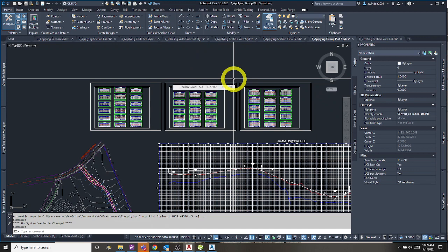When section view groups are created, there's 2 placement options. So these are critical as well: production and draft. And when a section view group is created using the production placement method, for example, the layout of the section view is made to fit to individual sheets. So that's ideal for if you want to put them in a sheet. The size and shapes of the individual sheets come from a template DWT file of your selection, which you might have to your exact company standards, for example. When the draft placement option, which we're going to see in a second, is used, the section views are laid out as a single group and aren't bound within a given area. So they can go past an area, for example.